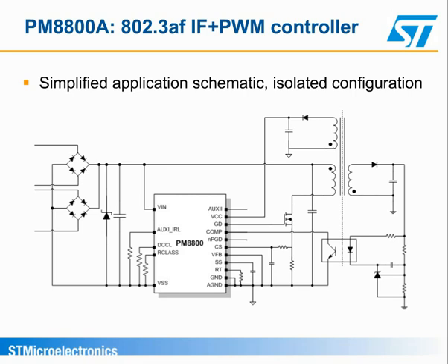A transient voltage suppressor, or TVS, is typically applied at the input of the powered device after the bridges, in parallel to a typical 100 nanofarad input capacitor required for the signature phase. The TVS absorbs the energy associated with the overshoot transient, ringing, etc., which may occur in the Ethernet cable. In typical designs, an SMAJ58A is used. This TVS has a standoff voltage of 58 volts, and its clamping voltage for a standard 10-1000 microsecond transient is 93 volts.